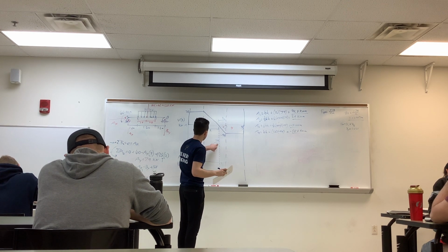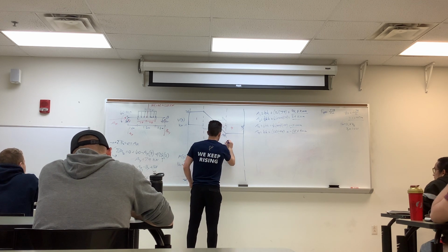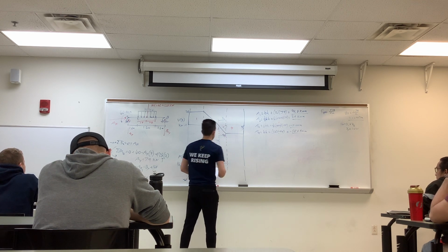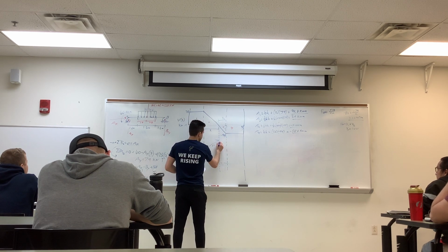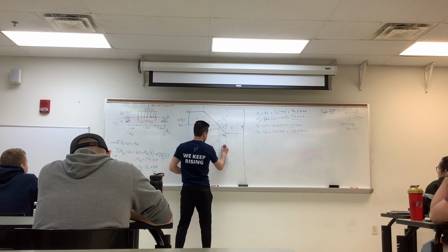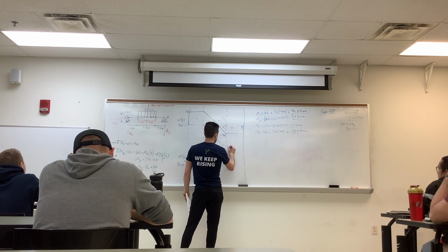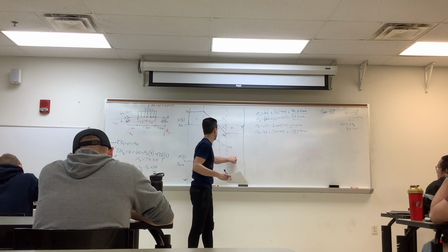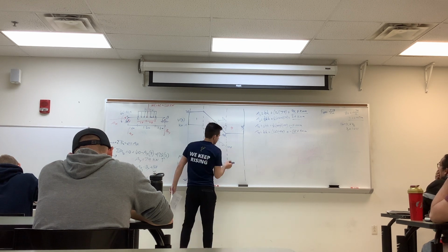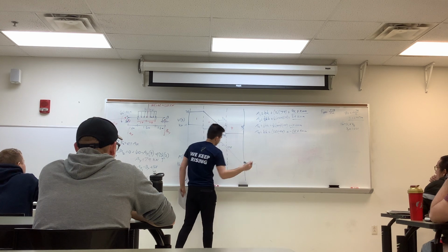From that point to point D, it'll decrease 15. Again, this is still the slope of x squared, down to 58.8. And then lastly, it'll decrease in a linear manner from point D to B, negative 58.8, ending back down at 0.